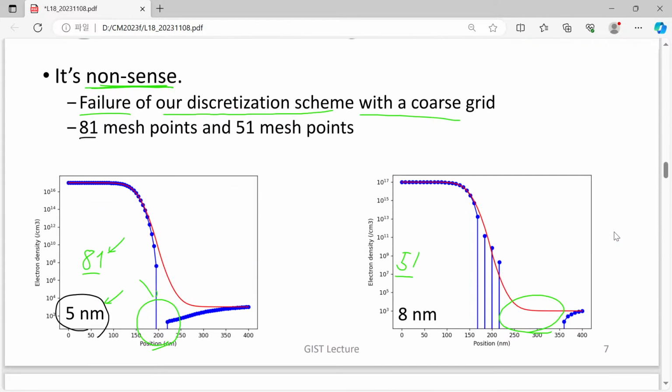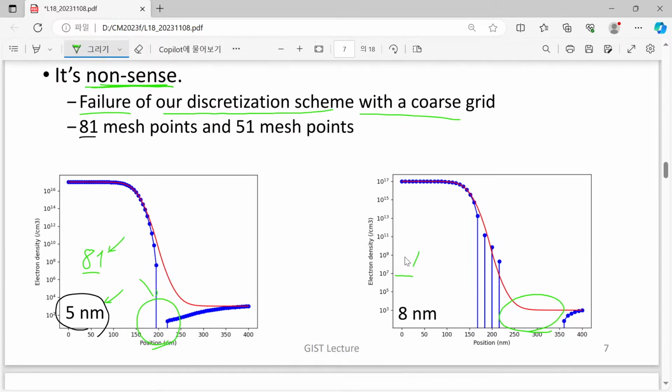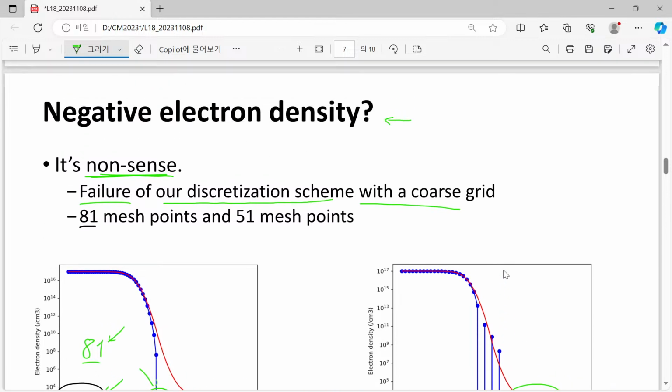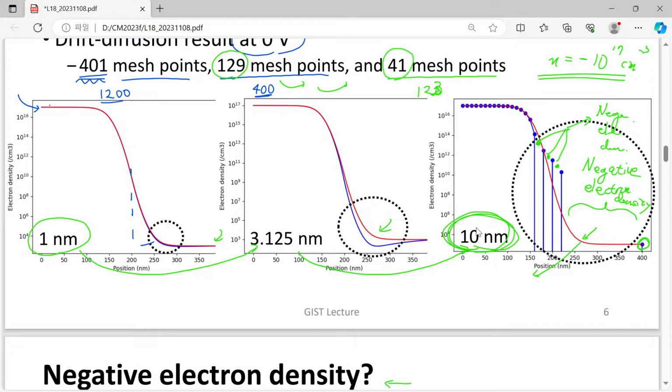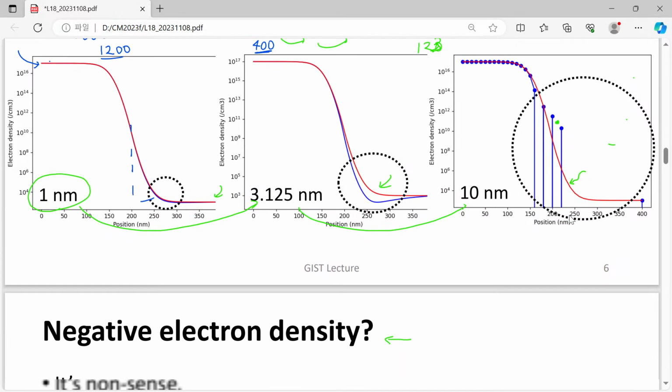The effect of the Scharfetter-Gummel scheme is quite obvious. I mean that even when you have this quite coarse grid, although your naive implementation clearly fails, your Scharfetter-Gummel implementation will give you exactly the same solution, like this red colored one. So that is quite robust, and that will give you some advantages when you apply it to realistic problems.